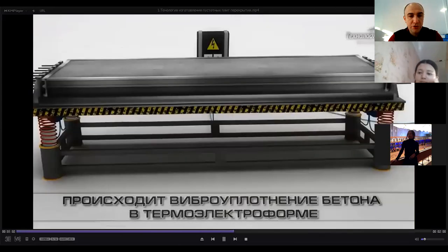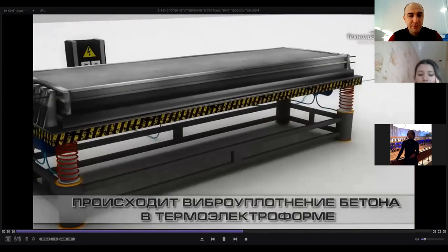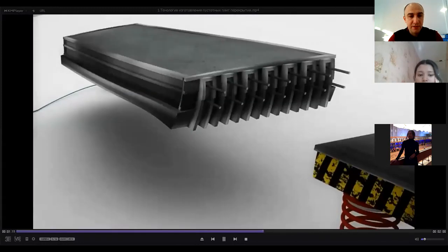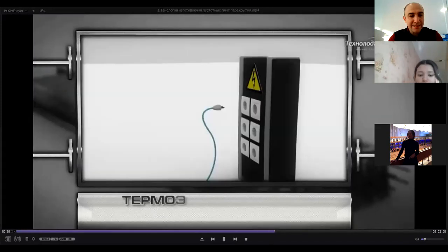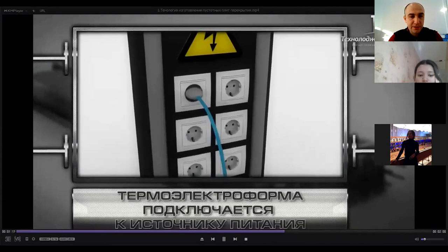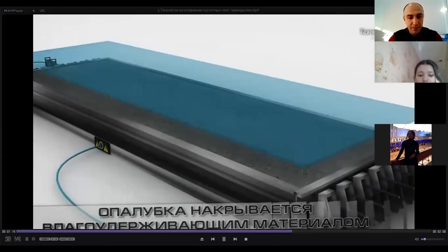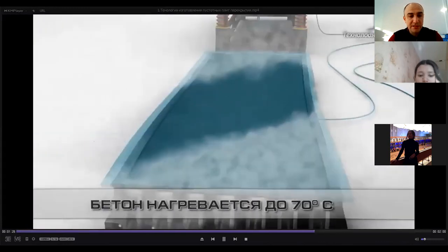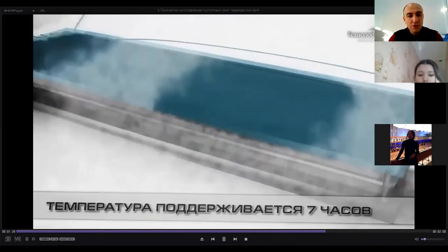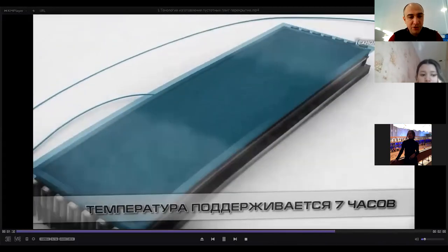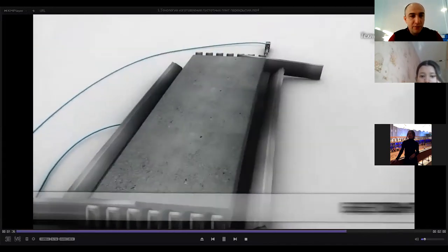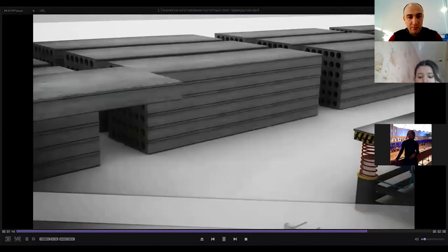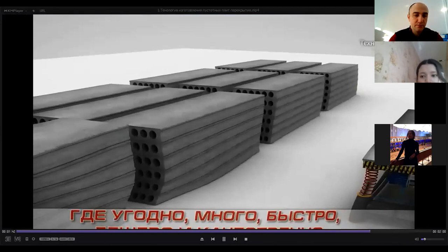Before concreting, the reinforcement was pre-stressed. Pre-stressing is an important part of creating the slabs because it increases their strength in bending, and it can increase the length of the slabs without increasing their depth. The openings made by special pipes decrease the own weight of the construction, but do not decrease its durability and strength.